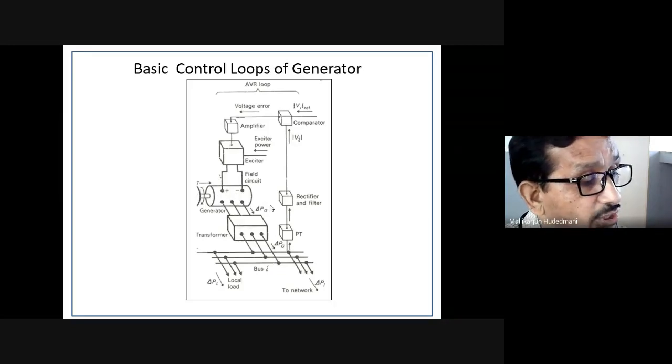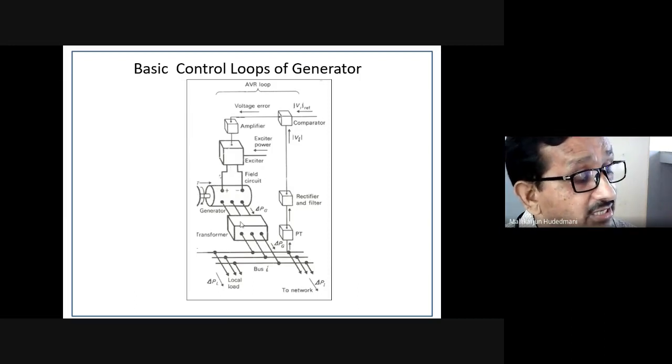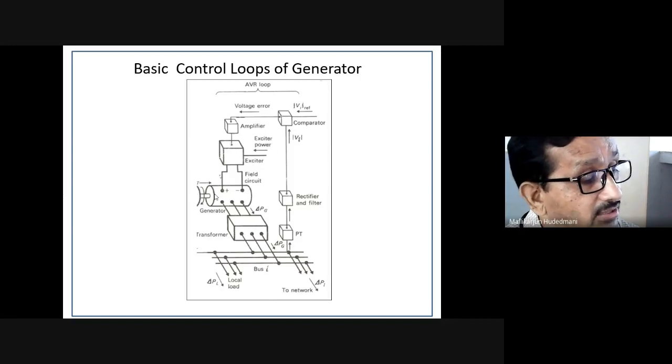So this is a synchronous machine and it requires a field input supply. So the field input supply is worked out by the exciter. Exciter is normally a DC generator, a DC machine which powers the requirement of a synchronous machine, in the ancient concept. Presently, brushless exciters have come into the real world. There is no separate DC machine. That particular concept is imbibed inside the generator itself, which acts as a rotating rectifier like concept. We call it the exciter.